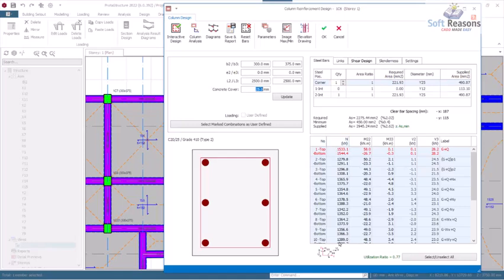We have the table here that consists of the numbers, which are the bottoms and top, as well as the loadings, and then the area moments. We have the shear forces and the levels of the loading combinations that you see over here, and then you see here we have the U ratio, which is 0.77, which is not bad.